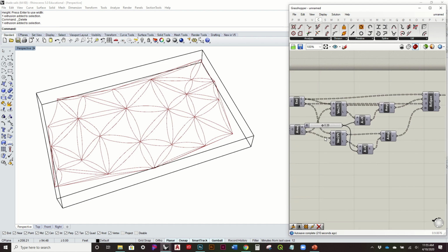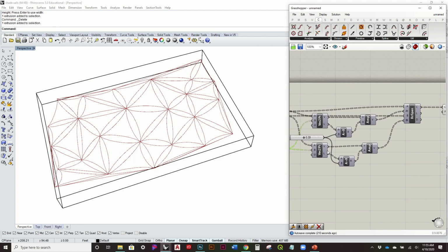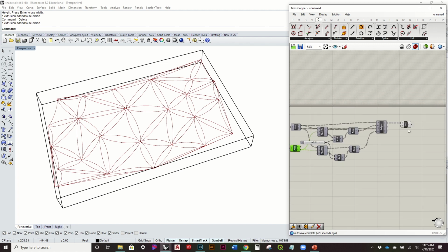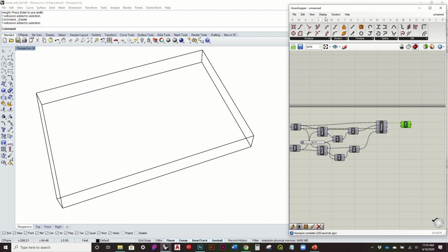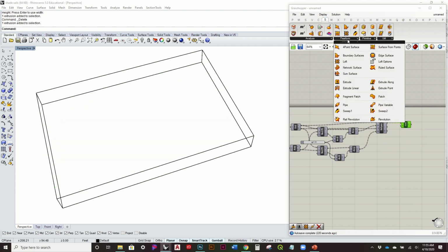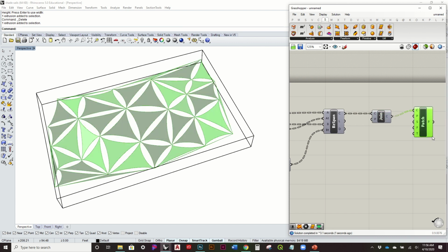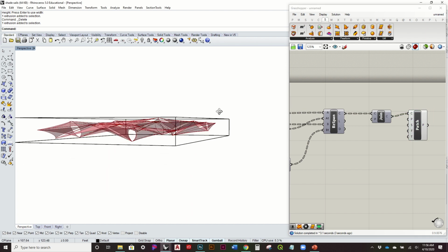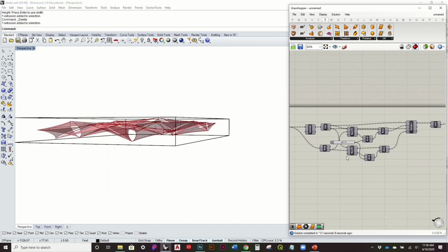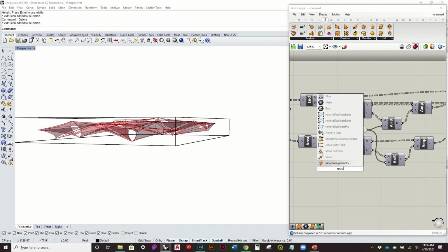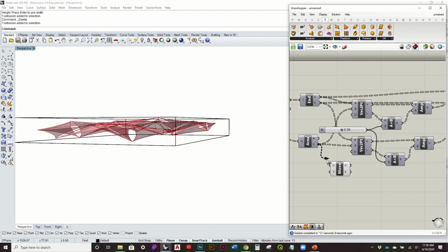And I'm going to, again, use my center points as a part of this. So I'm going to turn this off again, go to surface, freeform, and use the patch. And again, what's great is that's all grafted, so that's fine there. And the point, we want to actually move those down a little bit to give it a little bit of a dip.